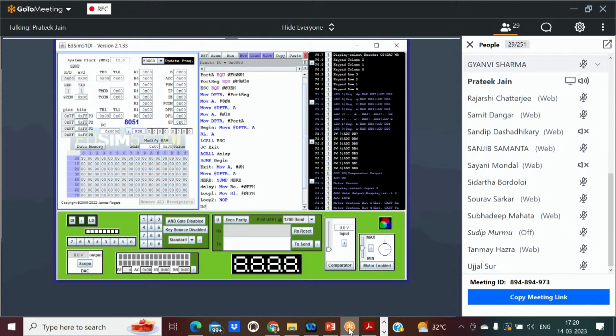And again for the NOP, this is DJNZ R1, assigned to the loop 2. And again this DJNZ R0 is assigned to the loop 1. So loop 1 and loop 2 can be carefully handled if you check the value of R1 and R0. Okay, because this is a conditional jump here. So now we are closing the command. It is RET, that is return, and that is the ending of the code.